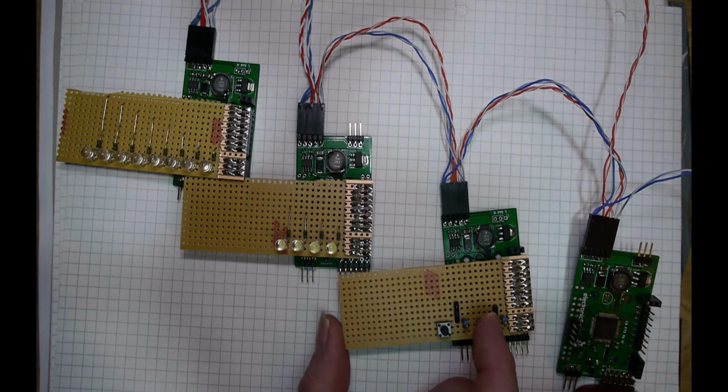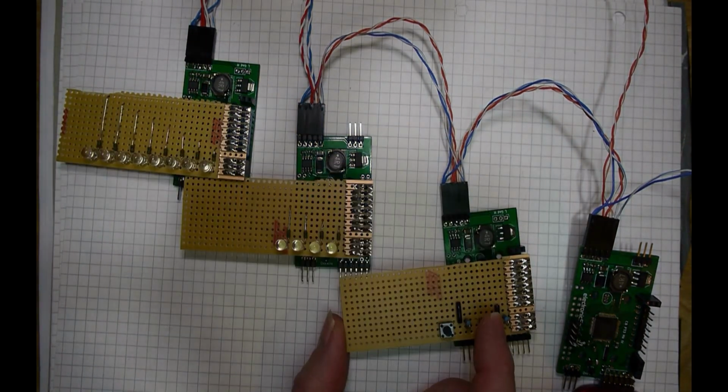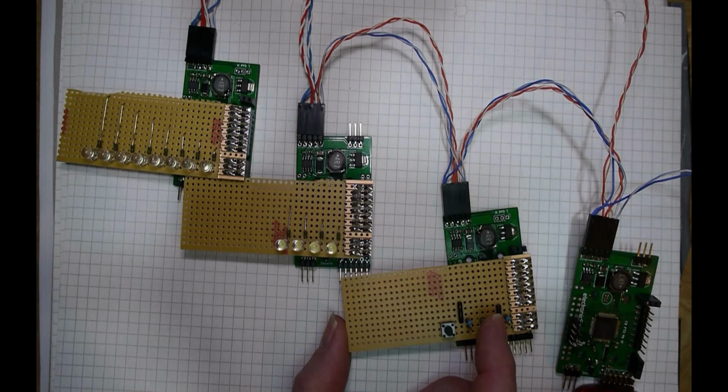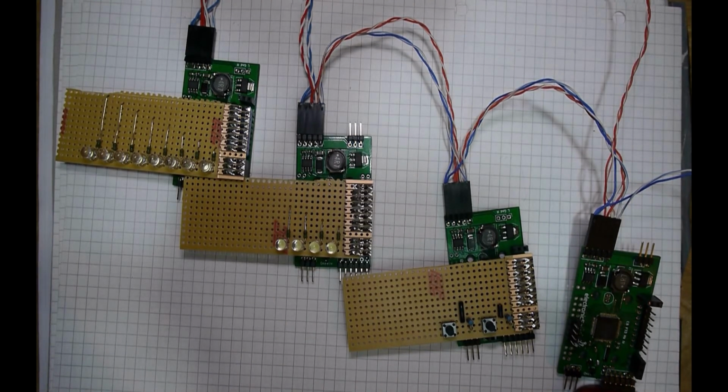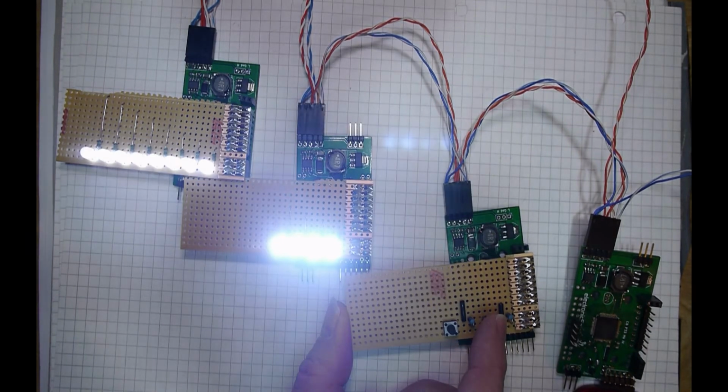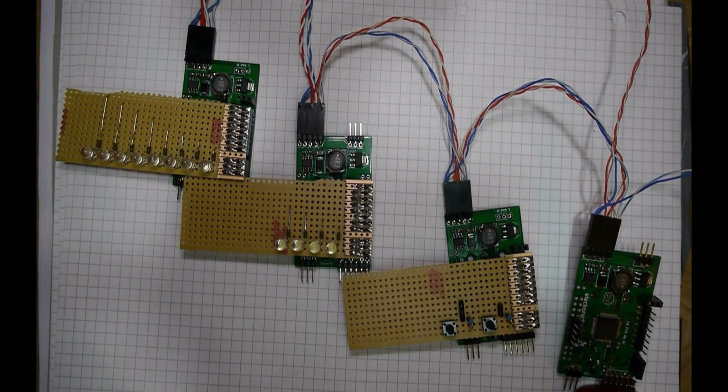But it's going to happen so fast. CAN bus is working at, I think I set it to 250 kilobits per second. So it's going to go much quicker than you can actually see it, unless the actual CAN bus network was busy with other stuff. But this is a very small network with only 4 nodes, and we're sending out those inputs. And that's pretty much it.